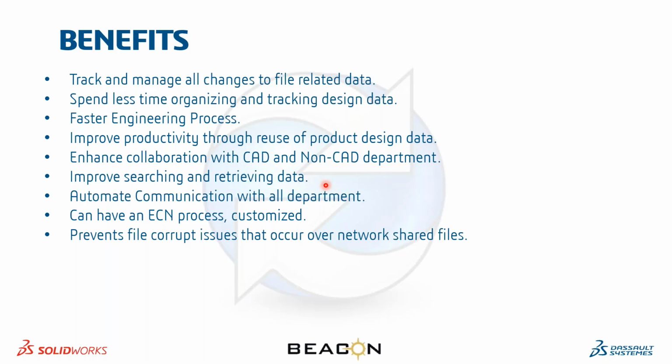In case something happens, like a network disconnection or a power disconnection, or anything happens to the server or the client systems, the files usually get corrupted, or they're not retrievable, or only partially retrievable. All those issues can be overcome with PDM, as it keeps track of versions whenever you do a check-in. Whenever you save and put a file inside the server, it keeps a copy of it. So even if something is lost, you can go back to the previous day's check-in and start your work from yesterday's data.